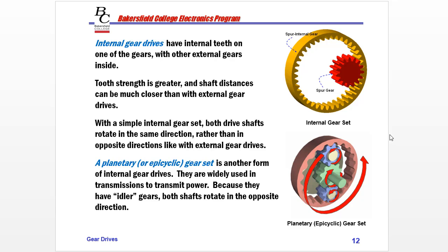So depending on the mechanical machine and the device, we may have just the two gears spinning in the same direction with offset shafts. So a motor would be attached to this side coming out of this red end. And then whatever we're spinning would be attached to the back side of the spur gear going this way. And so you can see those two shafts would be slightly offset. Where these are centered, one's in the center, and it would be connected on this side, driving from the other side of this red internal gear coming out this way.